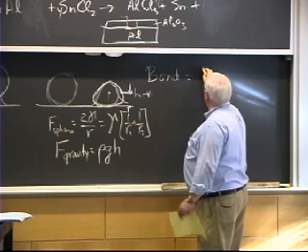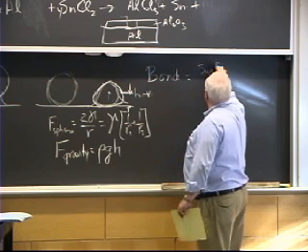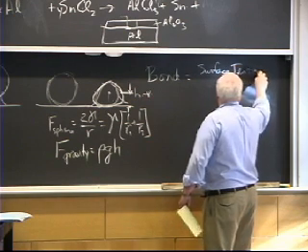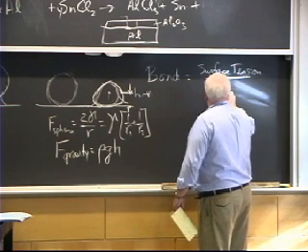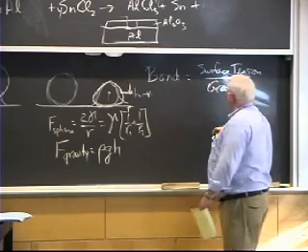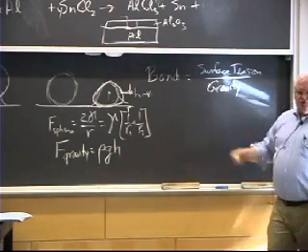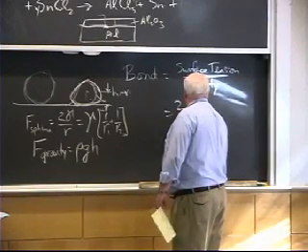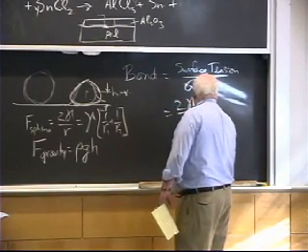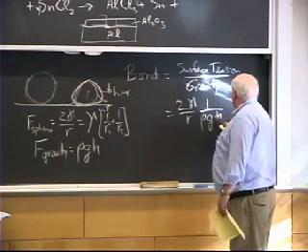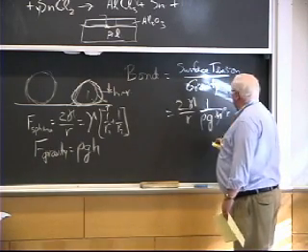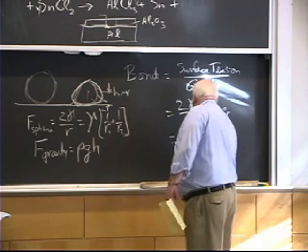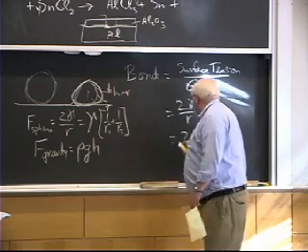The bond number is, I think, surface tension, or maybe 1 over the bond number; I may have it reversed, but I think I got it right. It's the surface tension force to the gravity force. Like any good dimensionless number, you're just taking these two forces: 2 gamma over r times 1 over rho g h, but I'm going to change that h to r, and I end up with 2 gamma over rho g r squared.